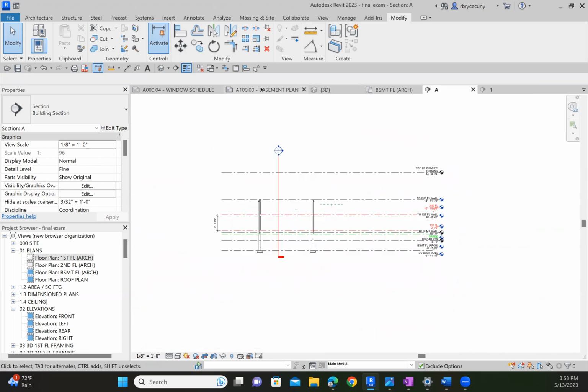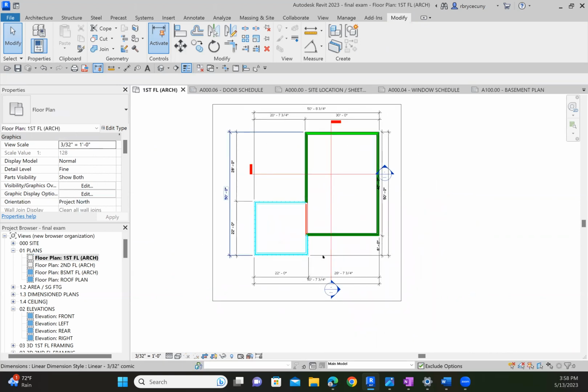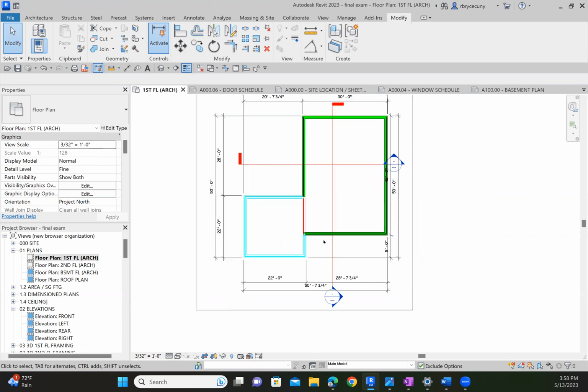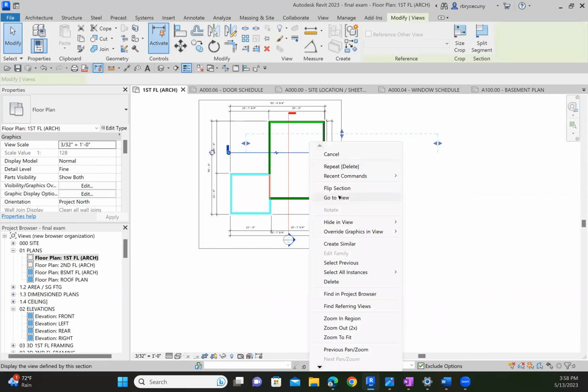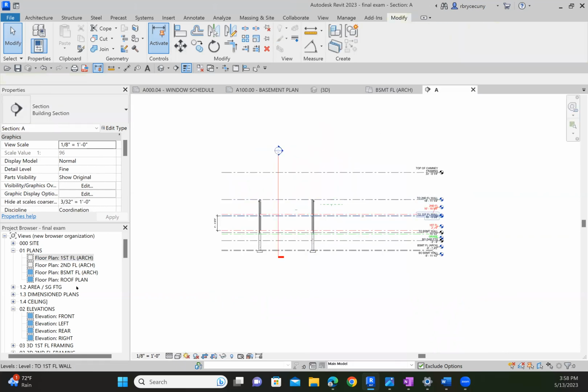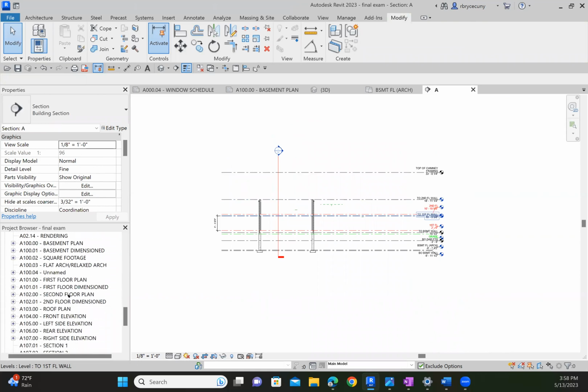So now when you go to your floor plan for setting this up for your final exam, before you actually do it, you're in good shape. When you actually create the outline and the interior walls the way you want it, then you can duplicate the sections by simply, let's click on that section and go to view. Now, the reason I did that is when I come down here, I'll see what that section is. It will be highlighted, so I won't have any question about it. It should be highlighted. It is.